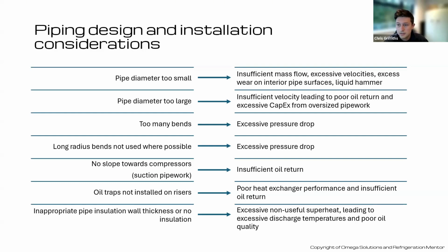On our suction side, if we don't install oil traps on risers, we'll get poor heat exchanger performance, because the oil will stay inside those evaporators and coat the surface a bit, so less heat transfer flows into the evaporator and reaches the refrigerant. And eventually that oil will build up at that part of the system, and your compressors will be starved of oil.